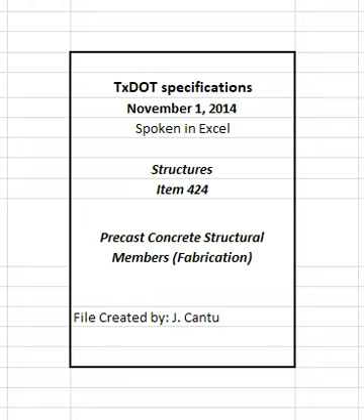4.2.2.2.3 Draped strand tensioning. Verify the intermediate load by observing either the gauge pressure or elongation and independently checking the other when draped strands are tensioned in a straight or partially draped position before application of final load. The intermediate or final load, if strands are tensioned in the final position, and elongation must agree within 5% of the computed theoretical values. Additionally, the intermediate or final load and elongation must agree algebraically with each other within 5%. Suspend tensioning operations until the problem has been identified and corrected in the event of discrepancies greater than these tolerances.